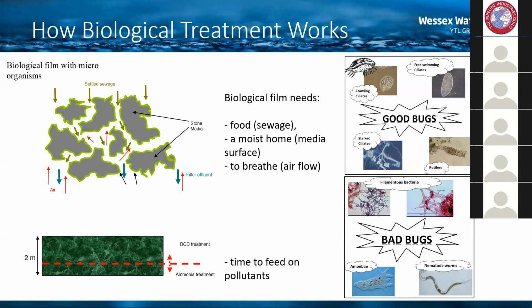bacteria. Where we get those in the process, you can get water caught between the strands, and they don't settle as well. So if they start to proliferate, we can get settlement issues with sludge, and you are at risk of a higher carryover of suspended solids in your effluent. So that's an example of a fixed film growth process.